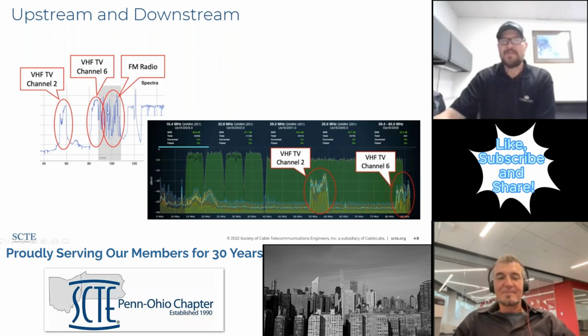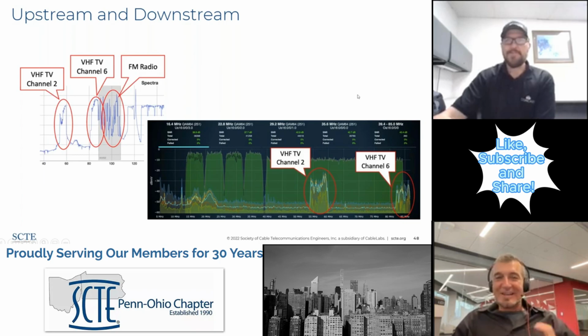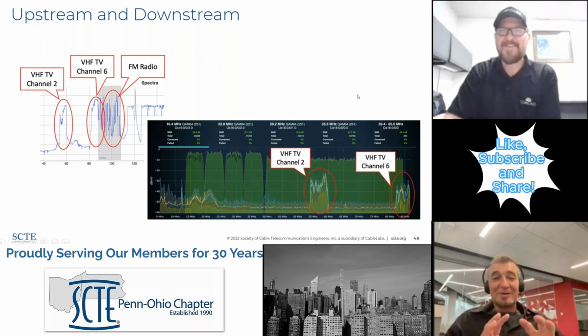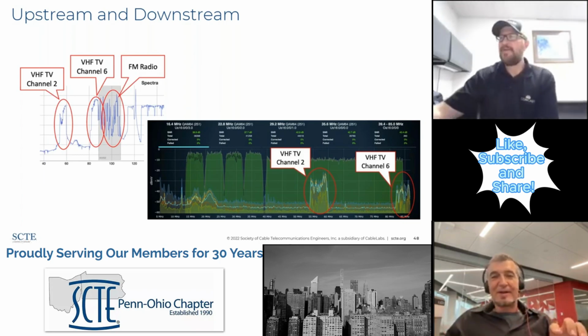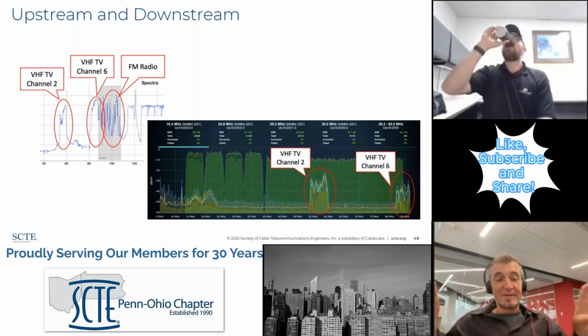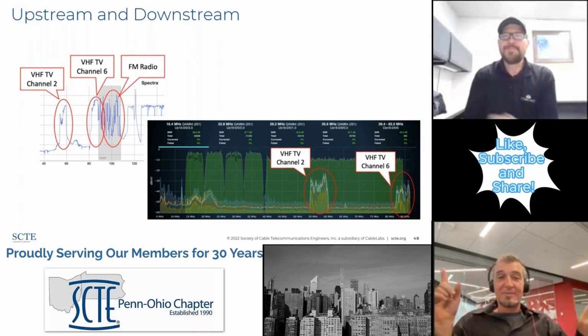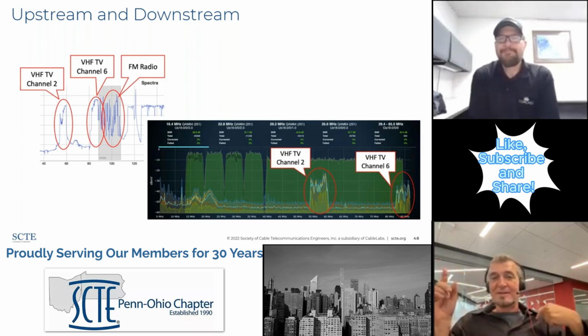So this one also has very persistent and high-level RF or FM radio noise, but you can see VHF channel 2 and channel 6 on some devices interpreted as downstream, and other devices interpreted as upstream. Tricky. That's why I put the slide in there, Mike. Remember, what you're looking at, the graph down on the lower right-hand corner is the head-end view. That's from the burst receiver. And then the graph on the left side is the cable modem view. So you're looking at the exact same impairment from different places on the network. One device considers it upstream, the other end considers it downstream.